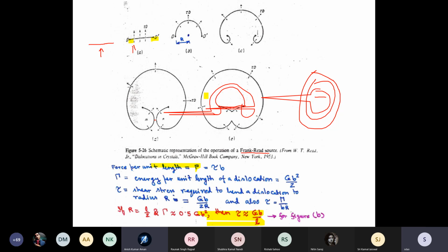You see, the folded metal is joined by riveting. One metal sheet end and another sheet end overlap. You make a tiny hole through them, put a pin through, and flatten both ends of the pin to join them. It's called riveting. So next time you board a plane, look at it. Its outside body is riveted, not welded.